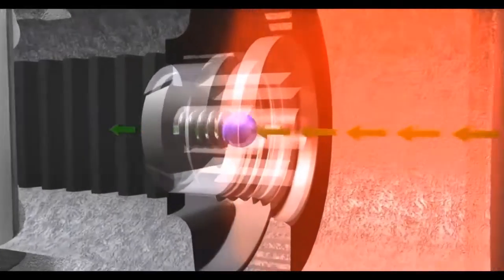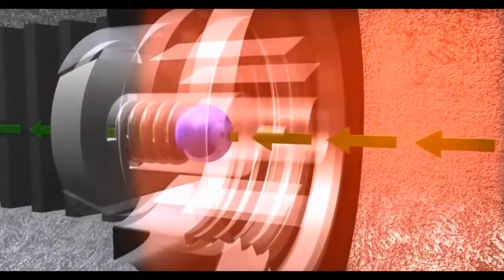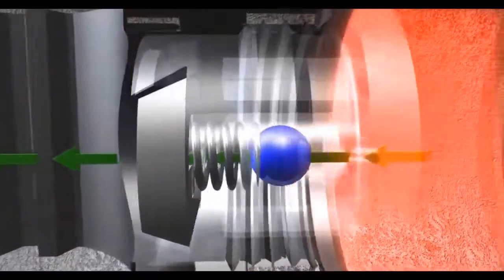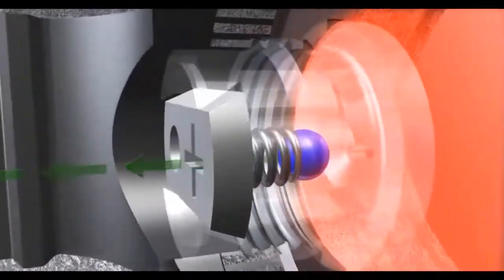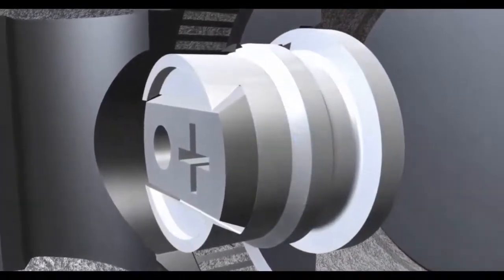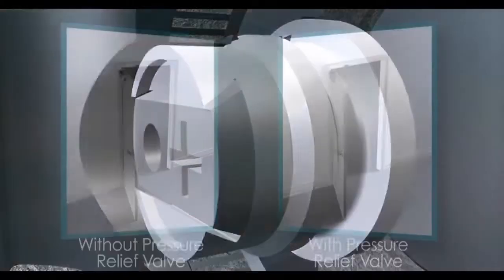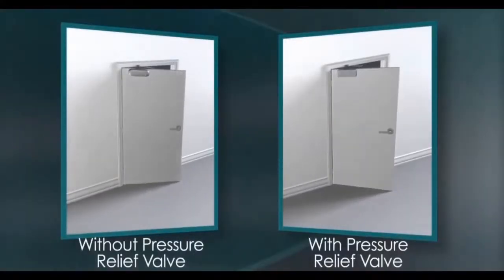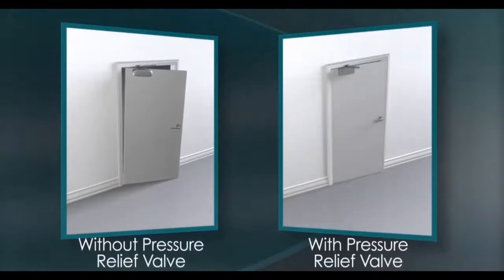The self-regulating pressure relief valve cycles rapidly during extreme pressure events to maintain control of the door. Once normal pressures are achieved, the pressure relief valve is no longer active, but ready for the next time the closer is abused. By releasing this pressure, the valve acts as a shock absorber, preventing damage to the door closer, the mounting hardware, the frame, or the door itself.